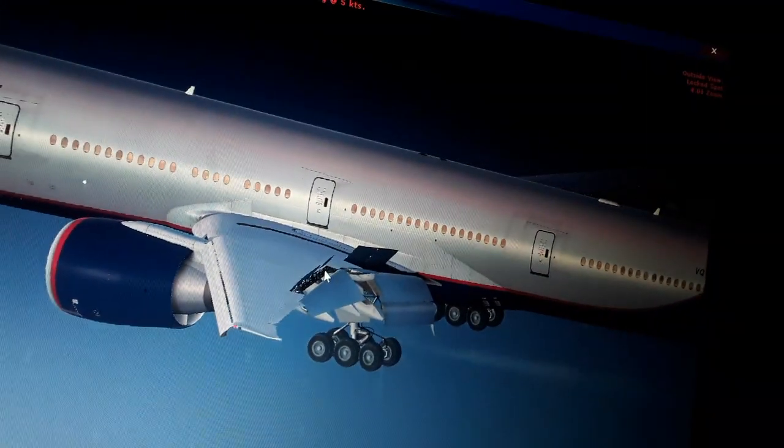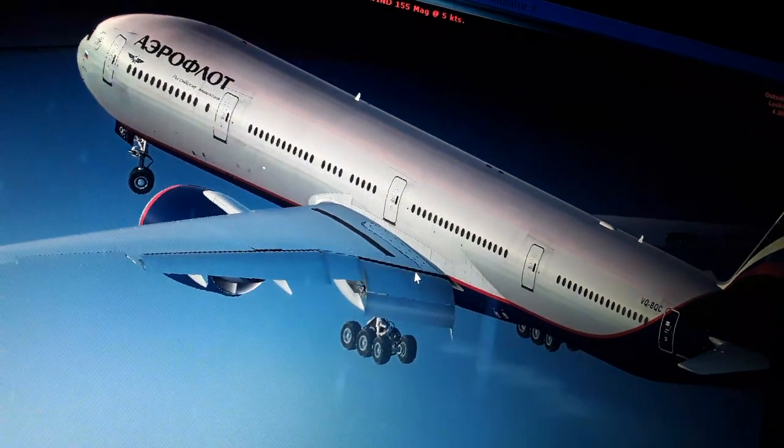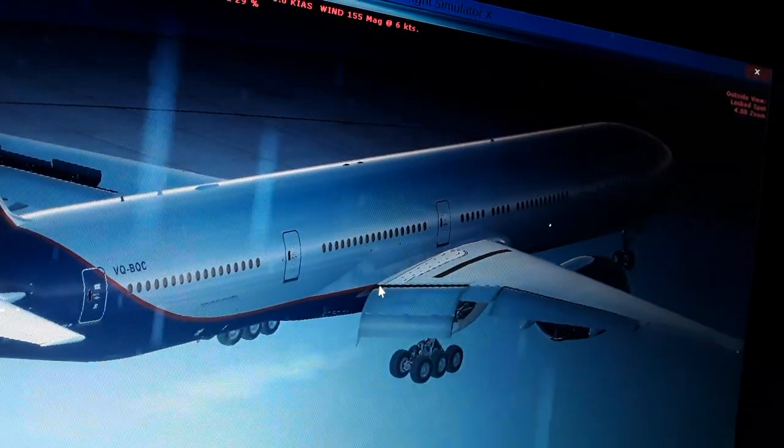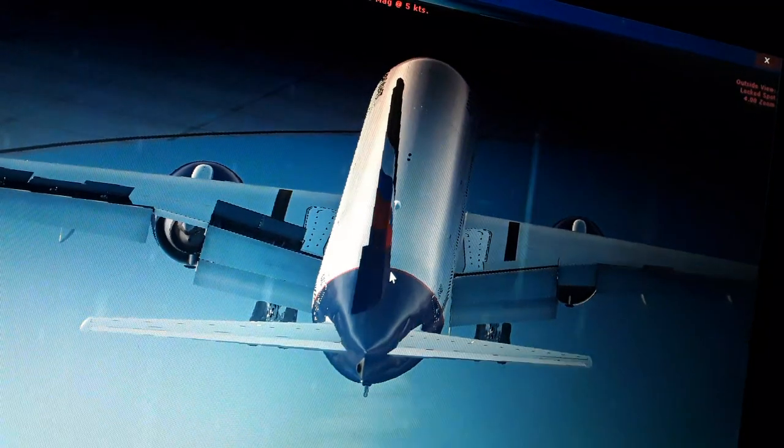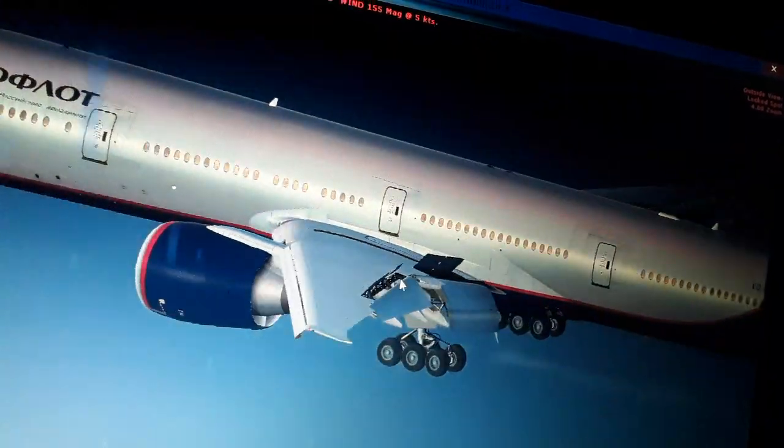You can see the ailerons and spoilers we use for directional control of the aircraft. Also the elevator and the vertical stabilizer. So we have quite a lot of flight controls. So the forward wings, about 35% of the mean aerodynamic chord position, creates the maximum aerodynamic lift pressure. It's the center of pressure. It's also the position where the center of gravity is usually positioned, so it makes the aircraft balance around this point.